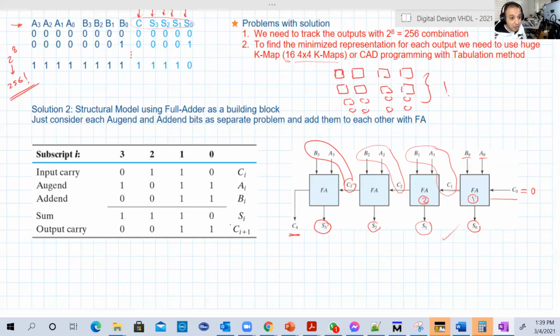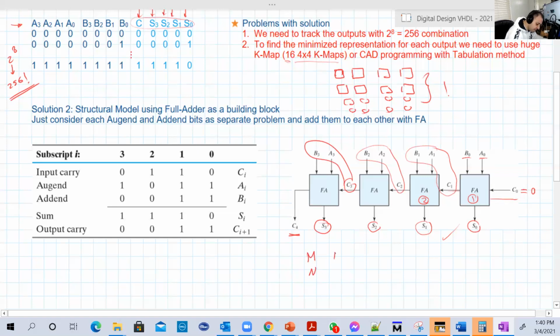Even if you have this input before and you have now 2 new numbers, 2 binary numbers that are less than 4 bits, it's also easy to use it, basically, because if you have, for example, another 2 numbers like let's say M and N, each one is just 3 bits, like M2, M1, M0, N2, N1, N0. You can still use the design if you have it already, and you will just put here 0 and 0 for the M3 and N3, which is not there basically.